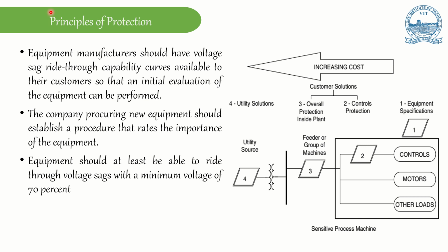So this is a small example I can consider. Inside the house, at different points, we use circuit breakers and also we use fuses. Fuses are for very local protection, and we use the circuit breaker for the next level. A fuse you can use for 1 ampere, 2 ampere, 5 ampere, up to 10 ampere, right? Once the fuse blows out under the abnormal condition, we have to replace it with a new one. So to avoid this, we go with the circuit breakers. For circuit breakers, you have 10 ampere, 15 ampere, 25 ampere, up to several kiloampere ratings. Accordingly, as the current rating increases, the cost also increases. But in case of an MCB, under abnormal conditions the MCB will trip, but we can restore it without any replacement of a fuse. So that makes the difference between the MCB and the fuse.